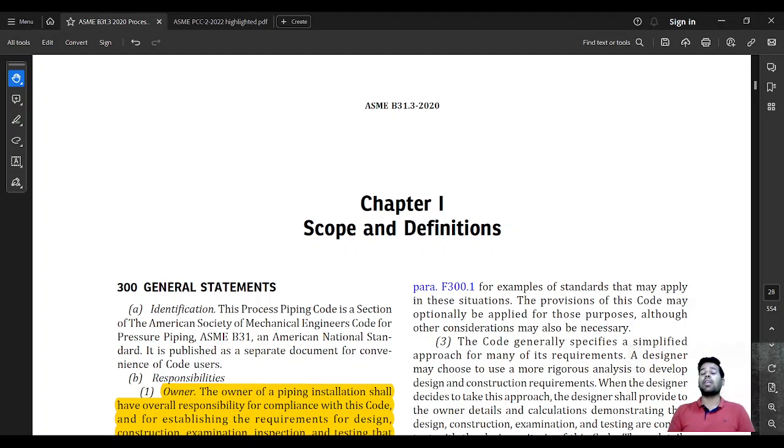But even if you are talking about in-service piping systems, some criteria are the same as when the piping was newly manufactured. So generally the heat treatment criteria, the pressure requirements, the thickness requirements, the hydro test requirements, all of these things are going to be similar for in-service applications as they are for new service applications.